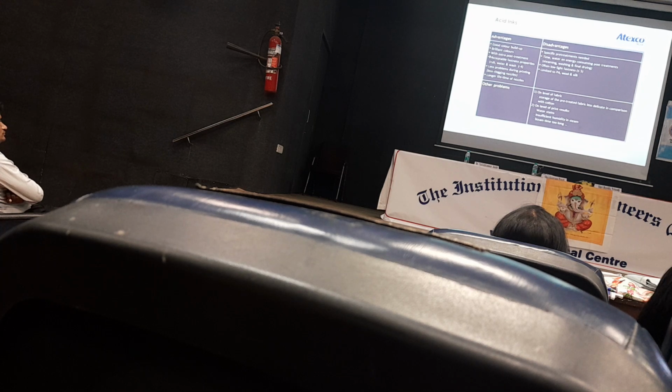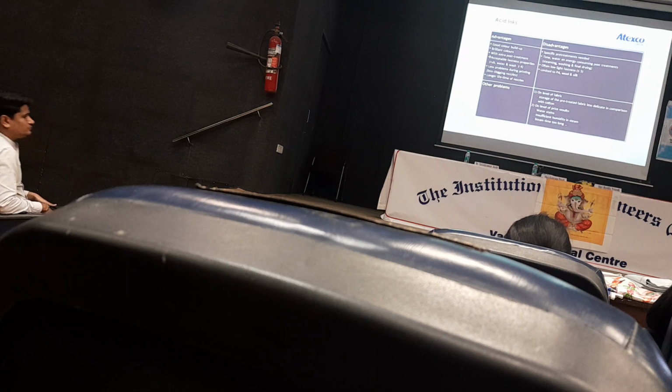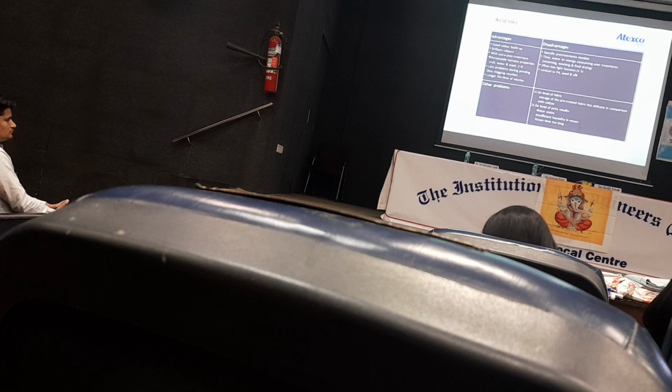The advantage of acid ink is good color build-up and brilliant color as well. Post treatment is required. But here the rubbing fastness is lower compared to other reactive dyes. And the clogging of the nozzle is less of a problem, so it is more durable for textile printing as well.